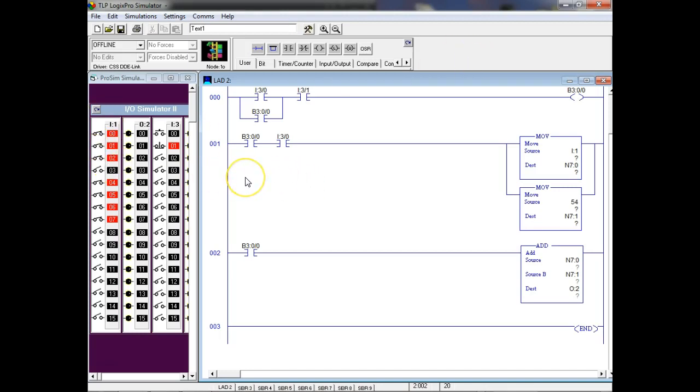So your retentive timer is the only one that needs to be reset. Okay. So undoubtedly it didn't like something, and what it didn't like, I can tell you. If it gave you an error code, a lot of times you can go into the status register and look at your error code, and then you can go on the internet and search what it means, and it might give you some more information. Are we okay? So y'all can put that, Rich don't know everything.